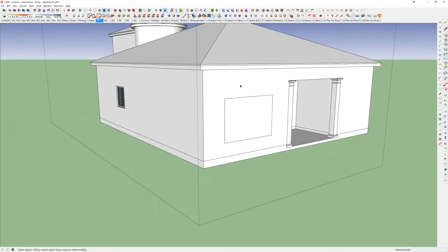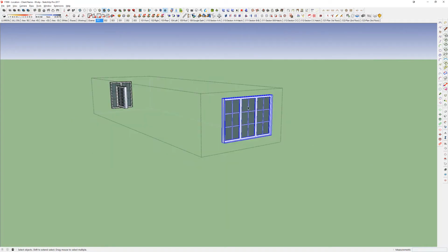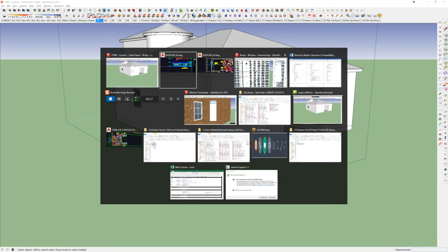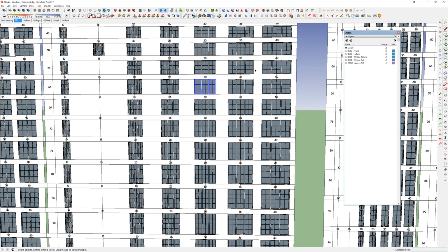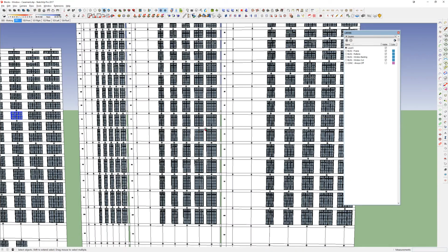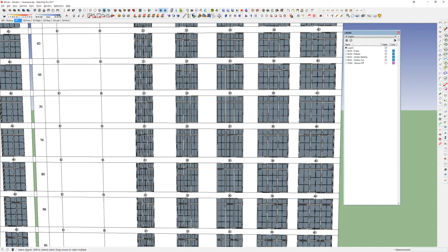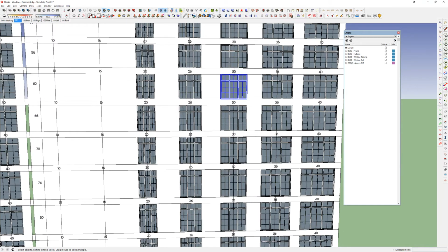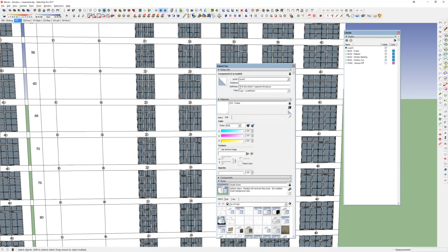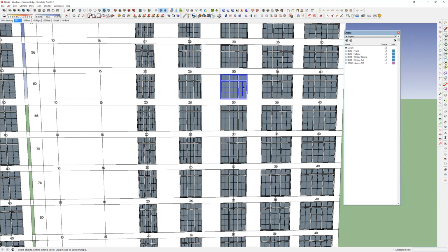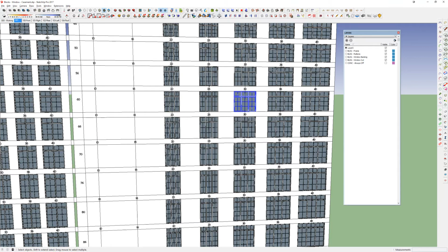So I'm actually going to, which is good because I want to show you something else, that maybe this window I want to have a transom over it. And since I put this one in already, I can actually switch it out real quick. Maybe it's easier for me to come in here, do my triple 3060 with transom. And again, you can see triple 3060 with 20 square transom casement enclosure. So everything should be named properly. In this way, it just helps you find things.